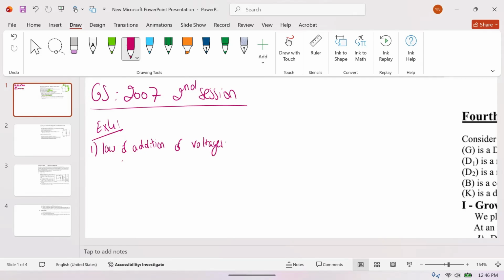Okay. What do we have in our case? We have the generator, and it's giving out to D1 plus the coil. Now, as I mentioned before, the voltage of the generator is E, the ideal voltage, minus Ri, with R being the internal resistance. Mainly, they don't give internal resistance, so we remove that part and we only end up with E. Now, about the resistor, UD is equal to Ri, using Ohm's law. This is everything we know about the resistor. Okay, so we already have I in this expression, so everything is okay.